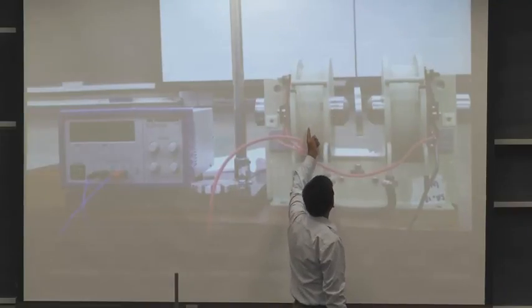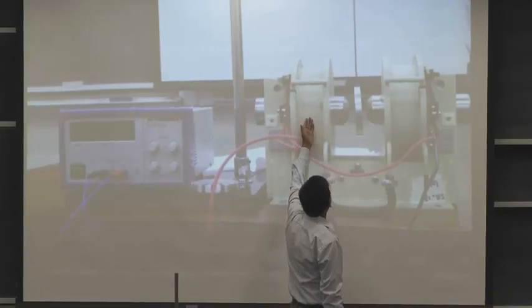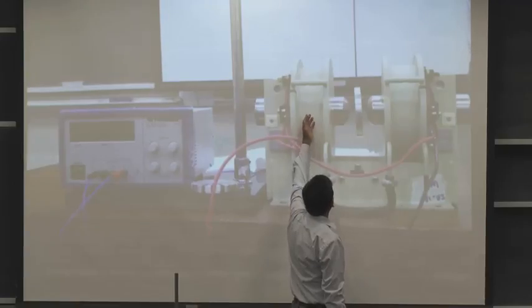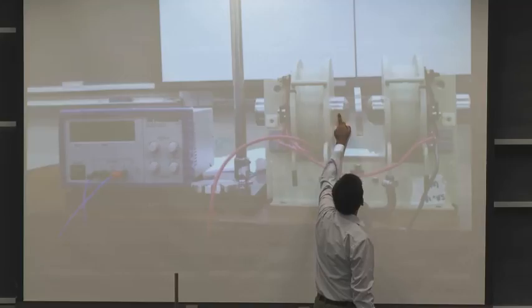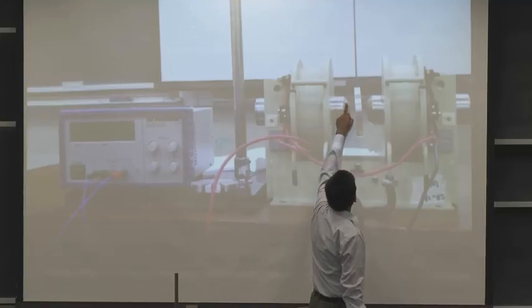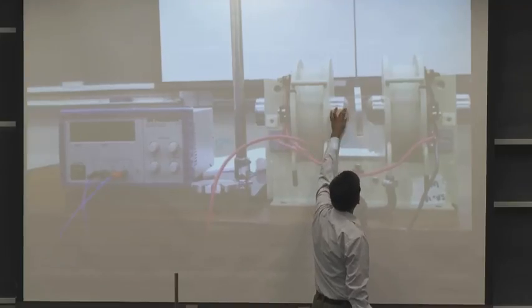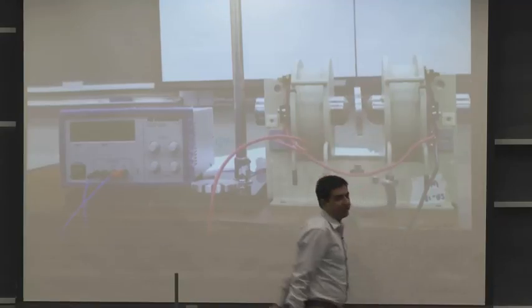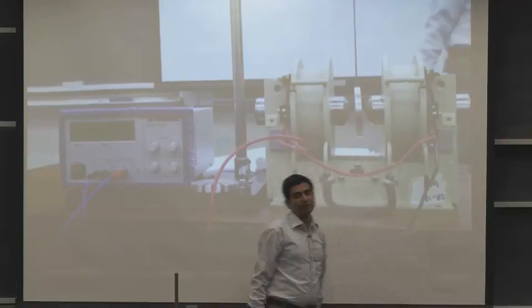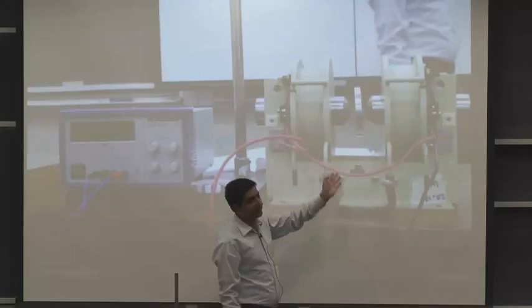The magnetic field lines don't in fact start everywhere. We can consider that the magnetic fields come from here. This is a soft iron piece. This is a tapered piece, so the field lines are concentrated and they go from left to right. They have to pass through air. They can't stop anywhere because of Gauss's law of magnetism. They have to be continuous.